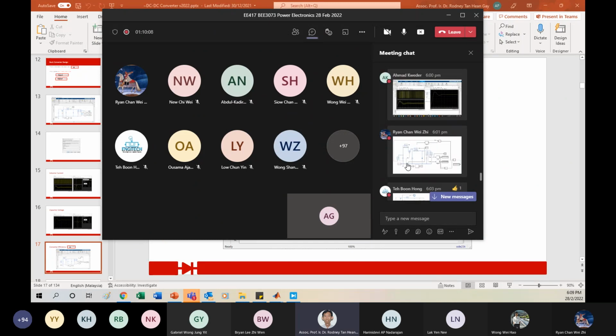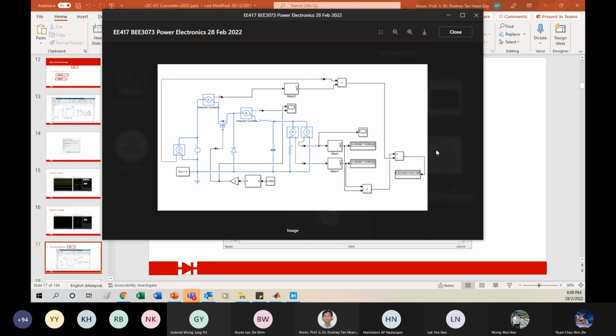Okay, Ryan, yours on here. It's not calculating. You got infinity, right? Wow. Infinity the first time, the second time 82 something. 82%. Something is very wrong. You see, your current here is 5 amp. Your R resistor, is it 5 ohm? Resistor 1 ohm. Wrong already. It has to be 5 ohm. 5 ohm got 1 amp. You have to look at my question carefully.